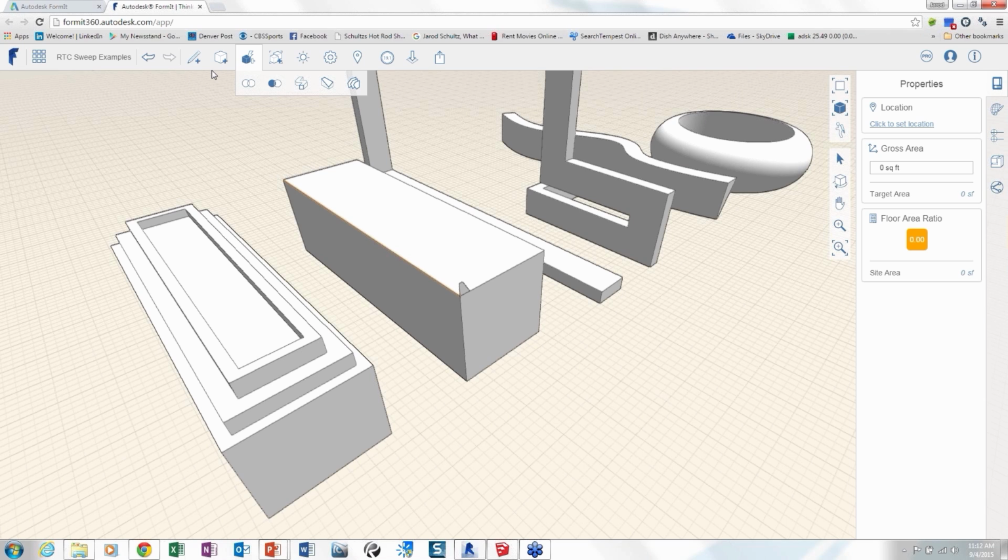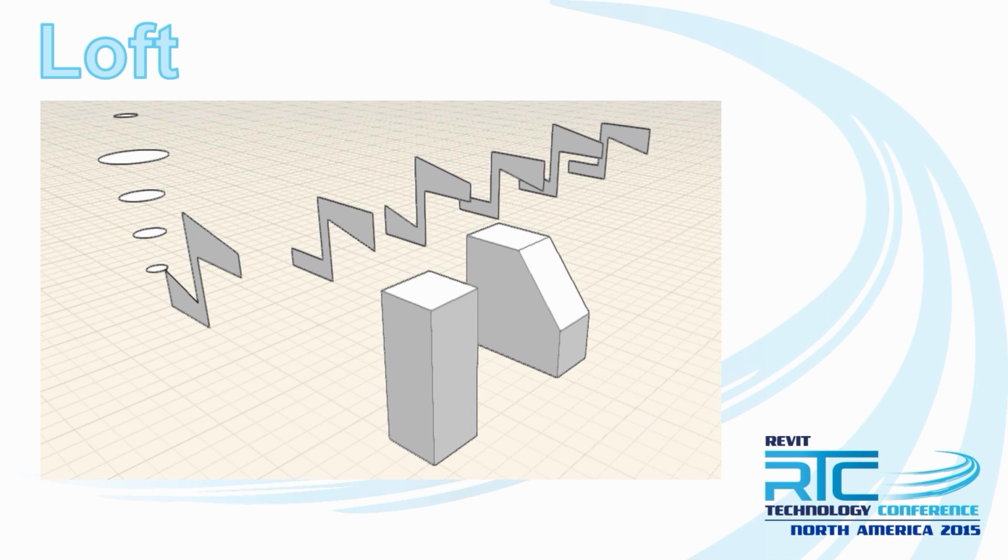Cool. And then a couple more questions. Somebody was asking about a beam form and being able to extrude a beam form, and I think that you can do that with the spline tool. As long as you connect the spline tool back around, you should be able to extrude that without any seams or edges going along with it. That's kind of a trick there, and that's under the drawing tools. It's the third option, the one to draw a spline. So that should work for that, and if it doesn't, then let us know. I'm trying to think if there were other comments along the way, but I guess that's pretty good for now. And we'll get to a couple of the other questions that are coming in.